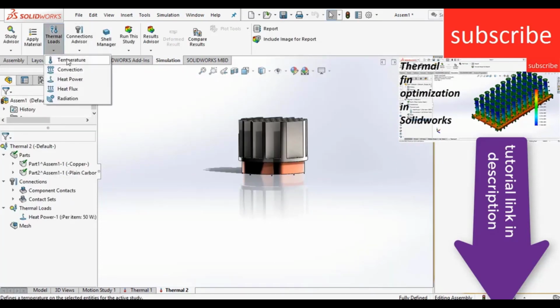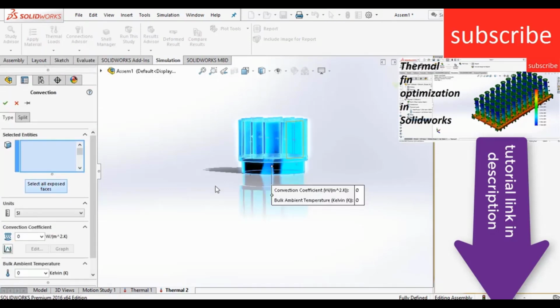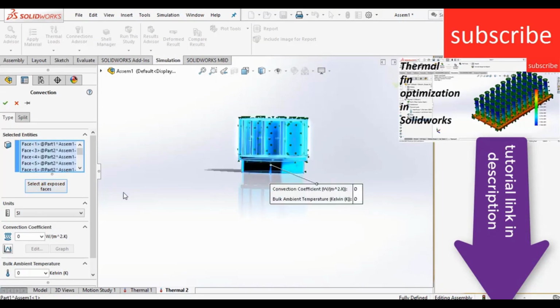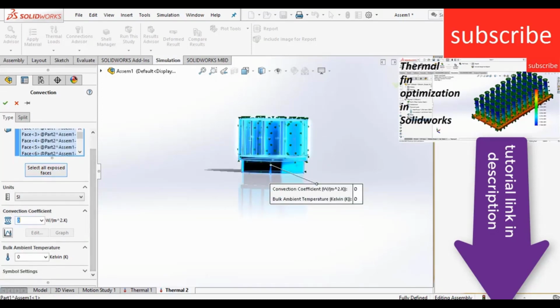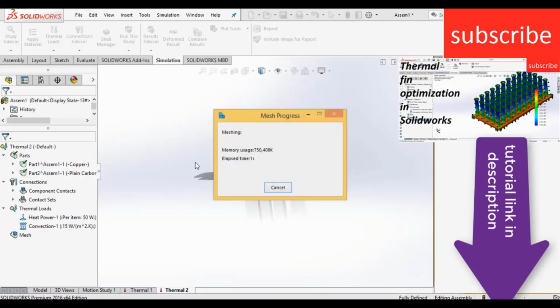After that, click on convection. Convection basically means that air is moving around, so click on select all exposed faces, uncheck the bottom part because heat is given at the bottom part. Okay, enter the value of convection as per your requirement, for example 15 watt per meter square Kelvin. Remember, I am going to make a mistake so that you will learn what kind of mistakes beginners normally make. So the result is going to be incorrect. I will tell you why the result is incorrect. So run this study.